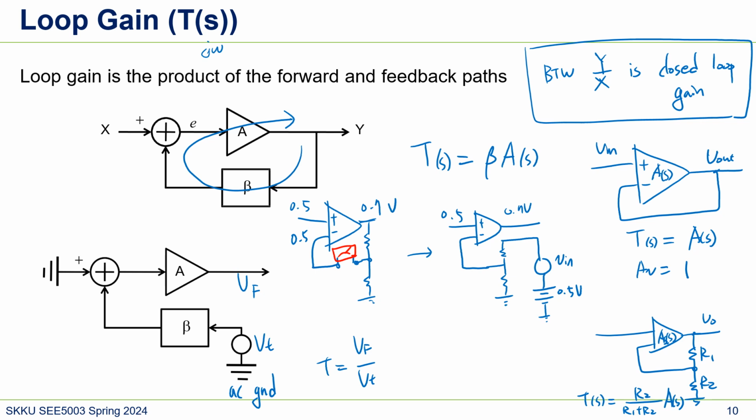It's like cutting the loop, but not actually cutting the loop. So it's like an iProbe, and with this simulation, we can measure the loop gain.